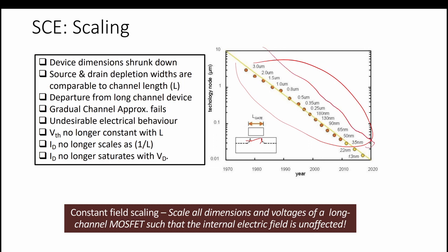Now we have around 4 nanometer or 5 nanometer of channel length. 4 or 5 nanometer is very less. We are going to the atomic scale. At that point, whenever we apply a voltage between these two junctions, there will be a current, so the channel is not turning off. The device is not turning off. What is the point of having a switch then?